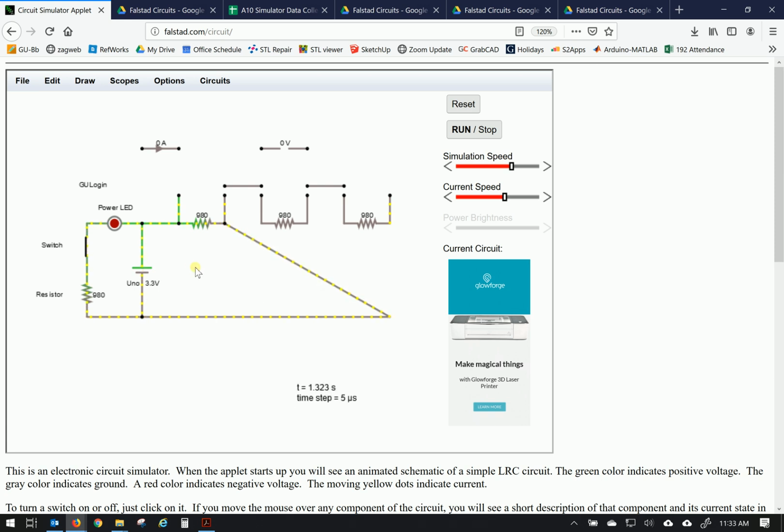So if you're observing the current speed here, you'll see voltage. The voltage from the power supply is pushing current through the circuit. So it's going through the resistor, but also out through the LED. And for now, we don't want to take a look at this. I'm just going to uncheck that switch so that now the current only goes through the circuit in one direction. Now, of course, we can hover over these objects in this environment, reading the voltage and current in the lower right portion of this window. You can hover over the single resistor.